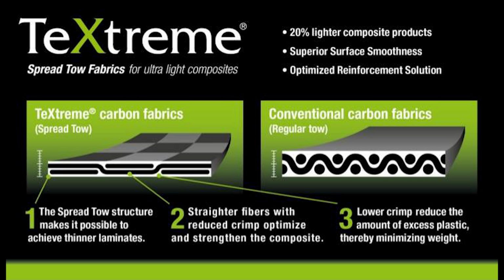Yeah, we only use this as our outer layer, and every square is like 25 millimeters. In an arm, if you're lucky, you can get one position without actually changing its position, and this entire weave is 0.07 millimeter thick in this laminate. So the angles when it's changing from top to bottom are just nothing. Basically, the fibers are going straight through in this layer.